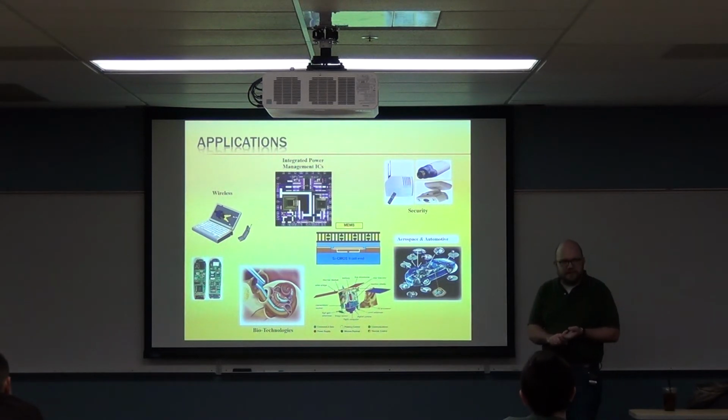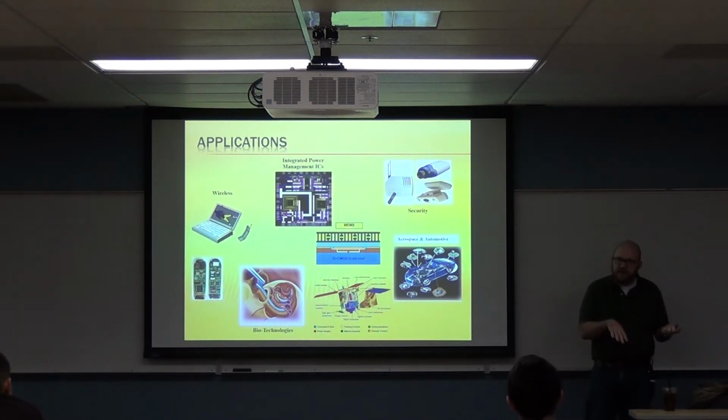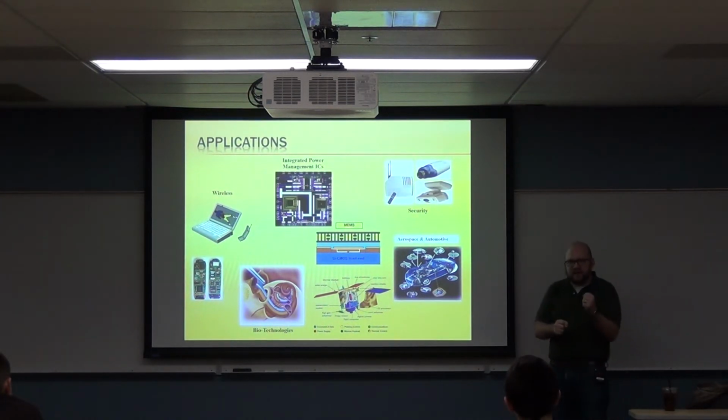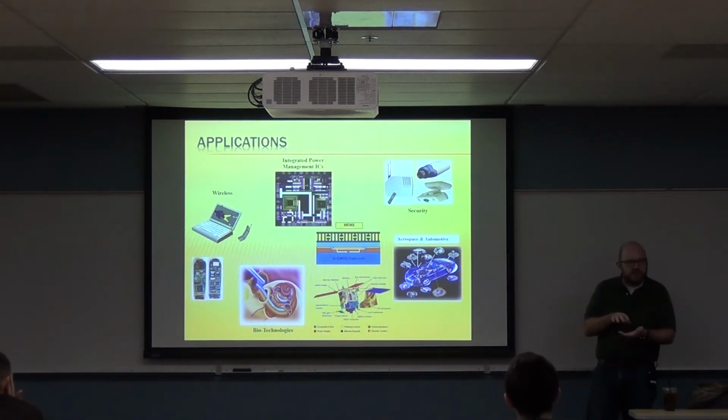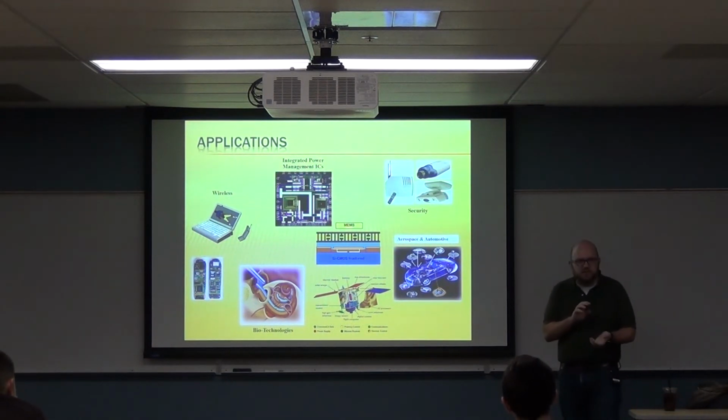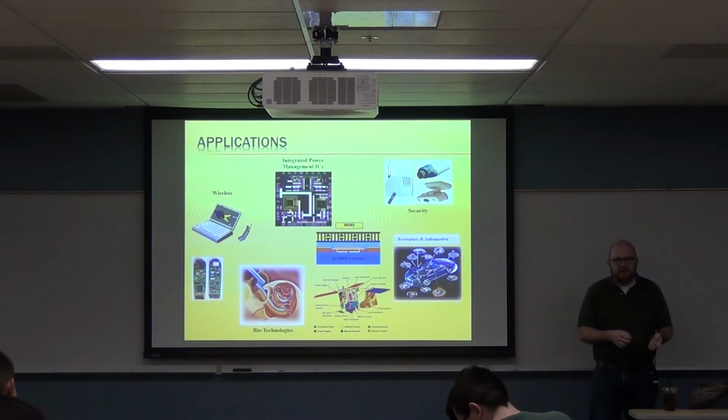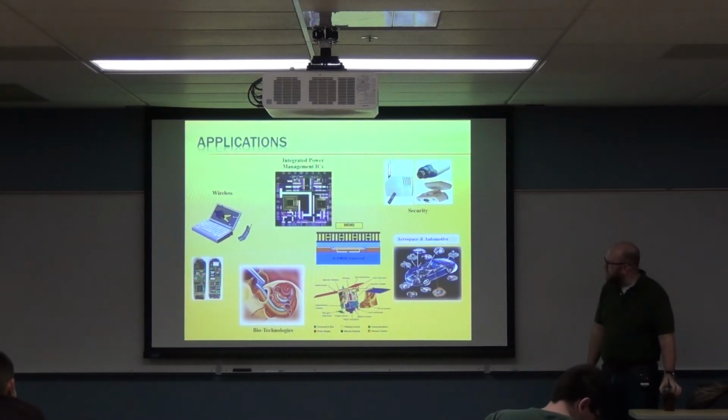So that thing that does the collision avoidance slams the brakes. But it needs to slam the brakes in a way that doesn't disrupt what the driver's doing, right? Because if the driver is turning at the time, that could be really bad. It also needs to do it in a way that doesn't cause a skid, right? So the anti-lock brakes is kind of this really neat classical controls problem. There are custom circuits that implement that directly because that decision needs to be fast and bulletproof. And so those are all baked in.